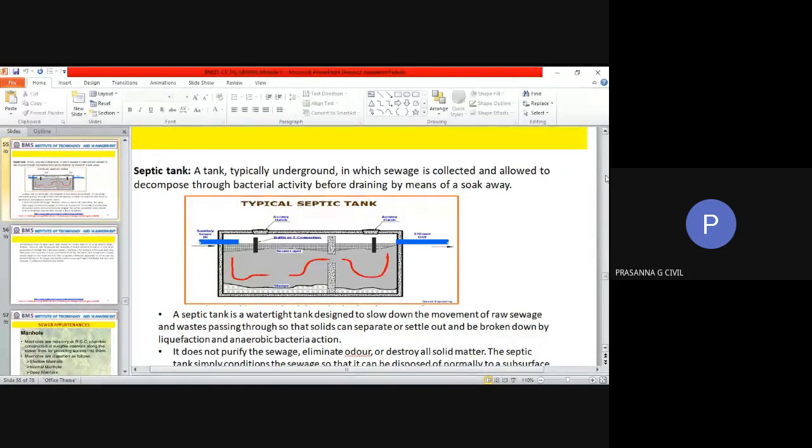And usually this cleaning in the previous years used to be done by manual labor. But nowadays, all of you have seen that vacuum suction equipment, which goes by the funny term of honeysucker. You can insert the tubing into that, and through vacuum suction, it gets pulled into an airtight tank. And so without much nuisance, the tank can be cleared out of the sludge.